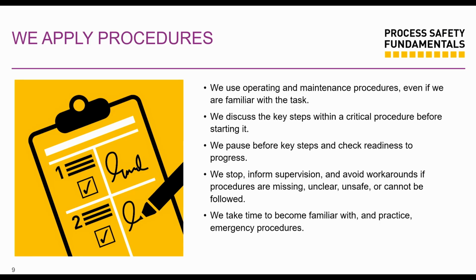Now, a couple of examples are, you want to start a gas unit, maybe a compressor, without following the checklist, because you just want to save time. Every time we're always in that mindset of, hey, we need to do stuff quickly. But then, you didn't pick up that a drain valve was left open, and then the gas escapes and ignites. So you should check your startup list and follow your procedures. And if you did that, probably that drain valve would have been caught in the procedure, and the procedure would have said ensure that valve is closed.